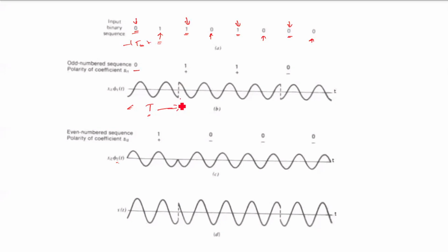So now here at this point, you have two signals appearing, right? So this binary sequence is going to modulate the carrier here, and this 0 here you can see is going to modulate the carrier like this, and so on, right? And the combined effect: this is one BPSK, this is another BPSK. Adding these two will result in QPSK. Okay, right.